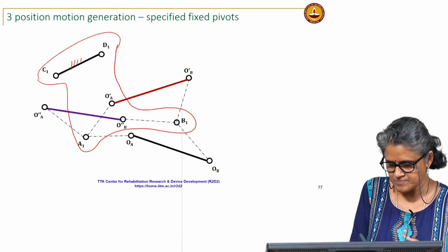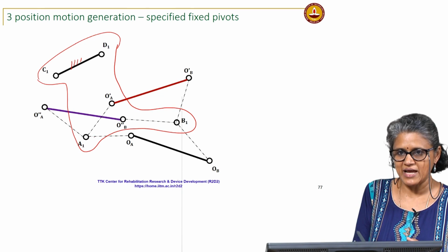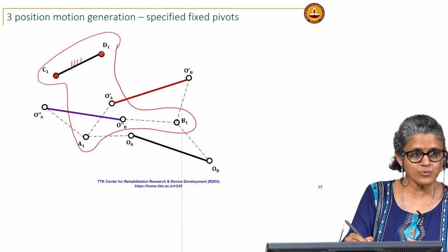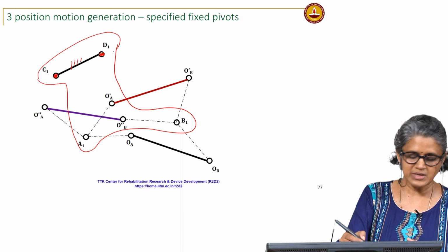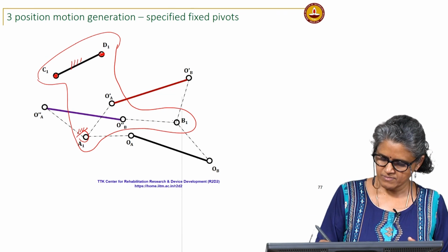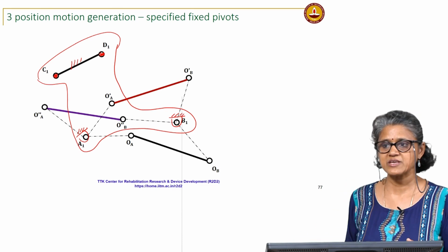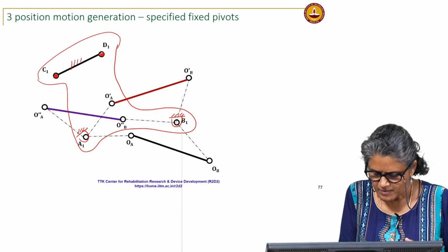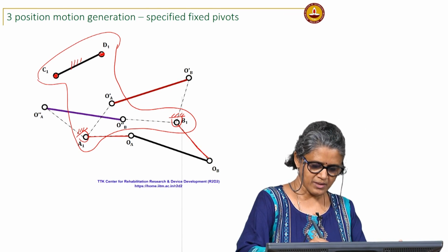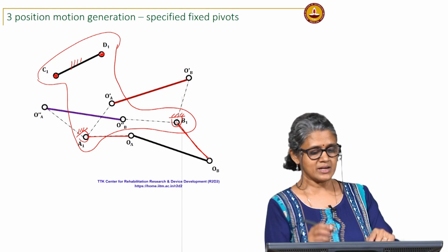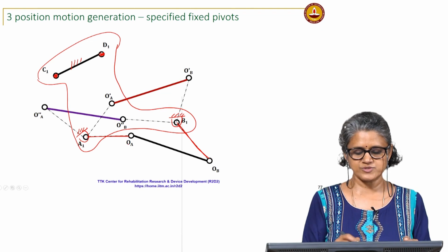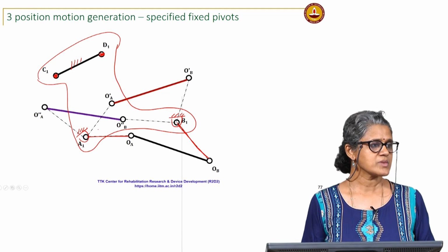So, again this becomes my fixed pivot actually. So, my link will not be the C1 D1, those would not be the pivots, right. These would be the pivots on the fixed link, and if I connect A1 to OA and B1 to OB, okay, then OA moves to OA dash to OA double dash, similarly OB moves to OB dash and then OB double dash.